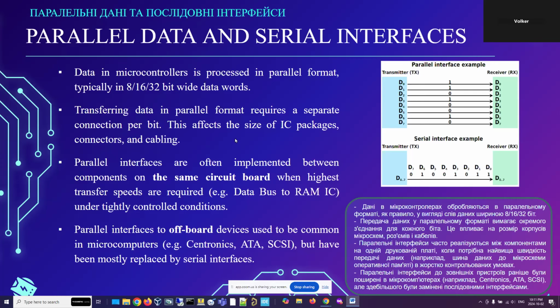several layers of circuit board layers to distribute the pins to the rest of the circuit board. So usually, once one gets to a size where a BGA package is required, at minimum a 6-layer board is necessary. And that makes debugging the board, testing the board more and more difficult, and the project more complex. It takes a longer time to develop. So that's what I meant with affects the size of integrated circuit packages.